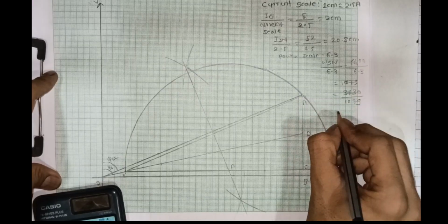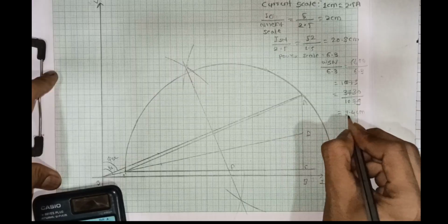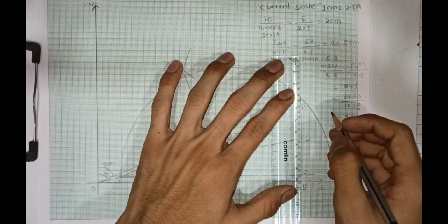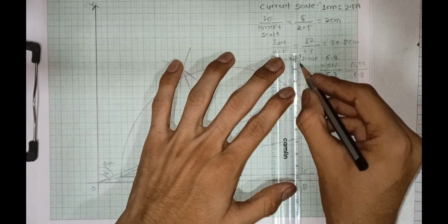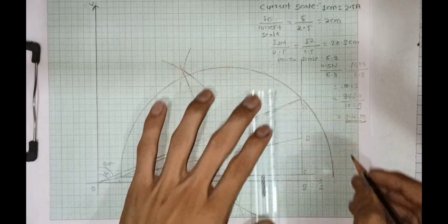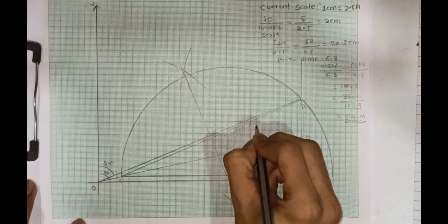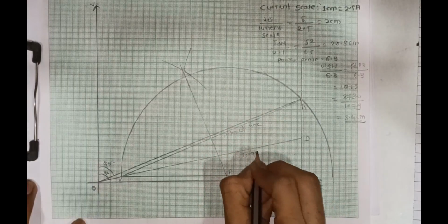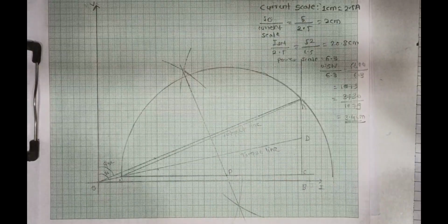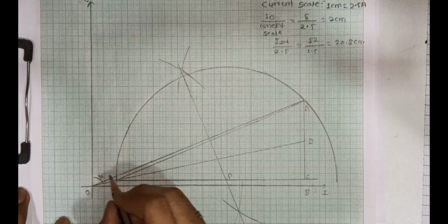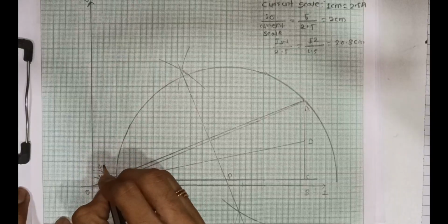As we know the induction motor is 5 HP, we have to convert that 5 HP into watts. We get 3730 watts. Now extend the line from A, whose length is to be 3.4 cm as shown. After doing the calculation, we get 3.4 cm. After that, mark the angles phi 0 and phi SC.